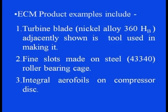The ECM product examples include the following. Number 1, turbine blade, which can be of say nickel alloy, which are very hard. The hardness could be as high as 360 in the Brinell scale. Adjacently shown is the tool used in making it. Then fine slots made on steel, roller bearing case, etc. Then integral aerofoils on compressor discs, etc.